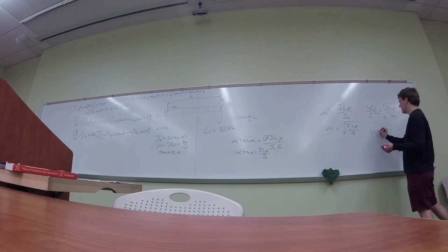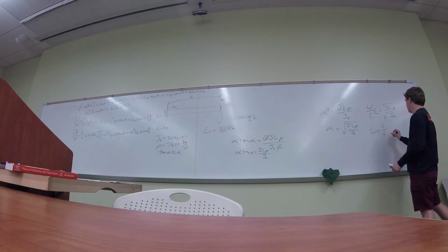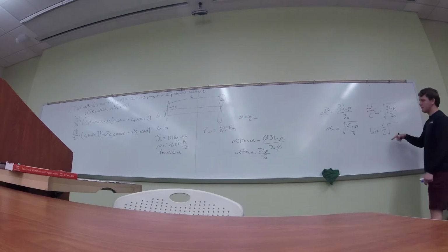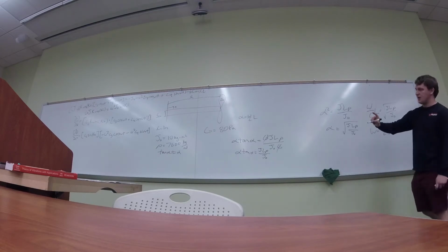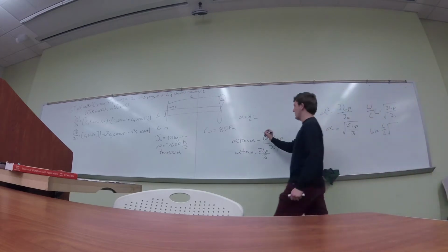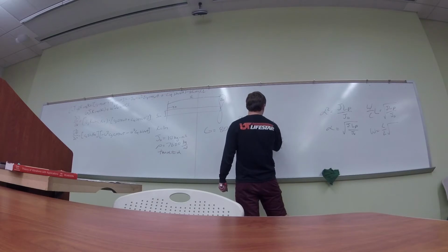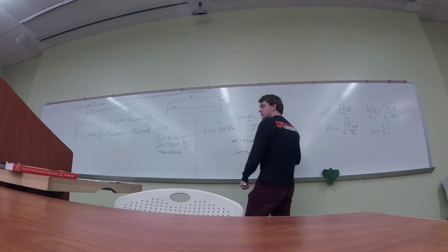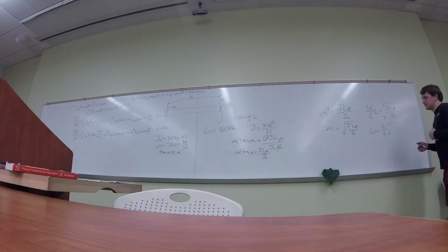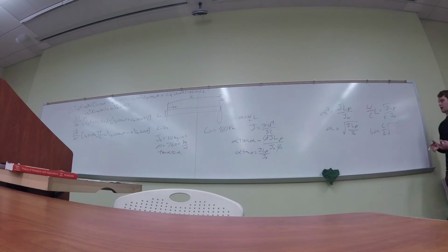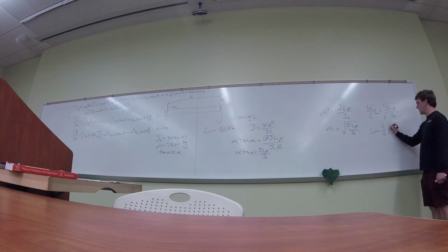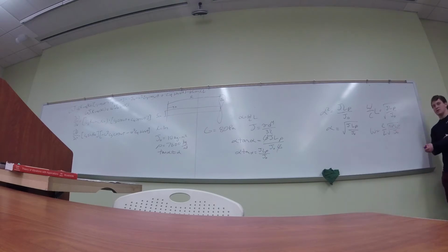So omega is going to be equal to c over L, and now we can even plug in J, which I erased, but J was equal to pi d to the fourth divided by 32. That's the polar moment of inertia. We can plug that in, pi d to the fourth L rho J naught, and you can get to this solution here.